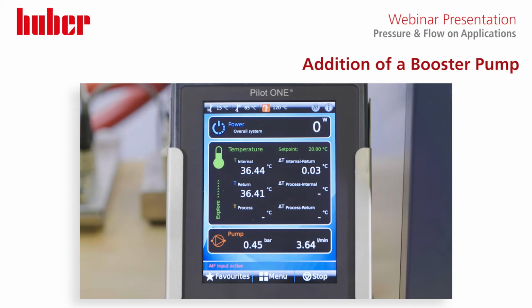What you'll find when you initially start up pumps is it's kind of the opposite to trapped air. You get cavitation because you've got a push and a pull system. The pump on the unit is pushing, whereas the booster pump is pulling the fluid in the feed line. So for the initial few minutes we might get cavitation, and you'll see the pressure dropping and going back up.